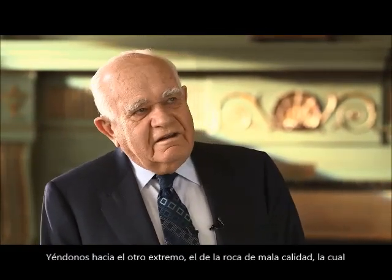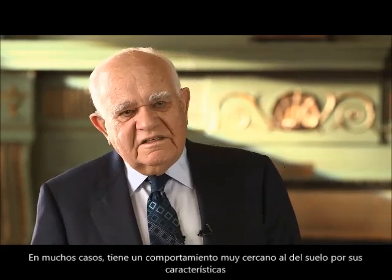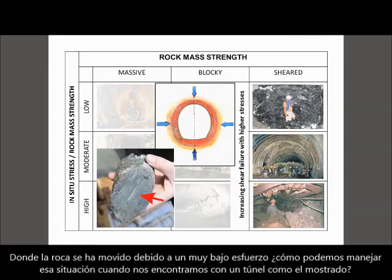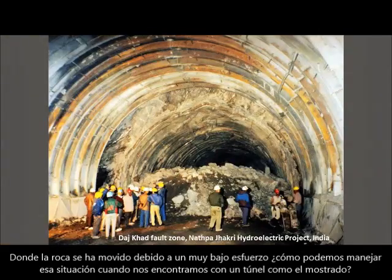Coming to the other end, the really bad rock, which is in many cases very close to a soil in its characteristics, and where you see this kind of surface in the core where it's been sheared. These are called slickensides, where the rock has moved and it's at very low strength. How do we deal with what happens in a tunnel here?